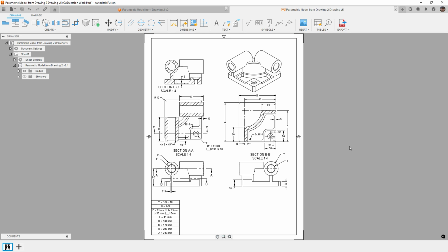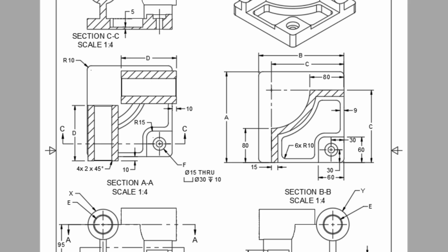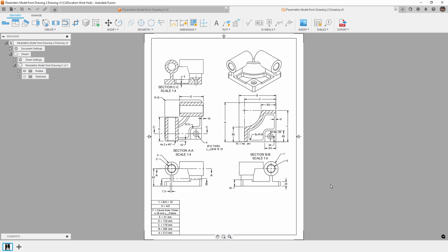When we're going from a detailed drawing to a 3D model, there are going to be some different approaches that people take, but my approach is to try to look at primitive shapes and think about the order of operations in which things were built. So what I mean by that is, as we look at this part, it has a rectangular base that is a specific height, in this case 25 millimeters. So in general, we can start by defining that base shape, which is the value A by B. So A tall and B wide, and then it's a thickness of 25 millimeters.